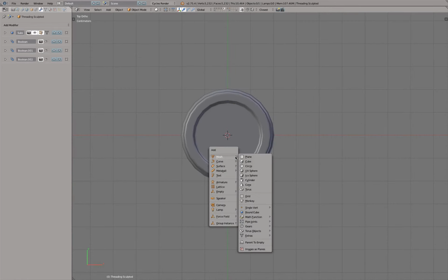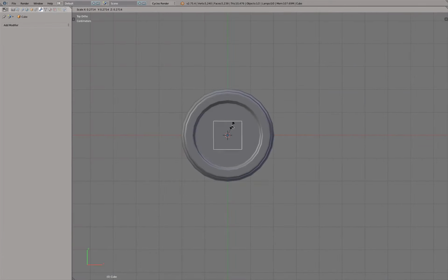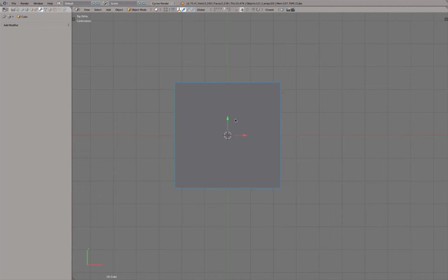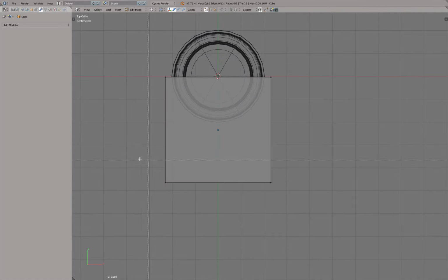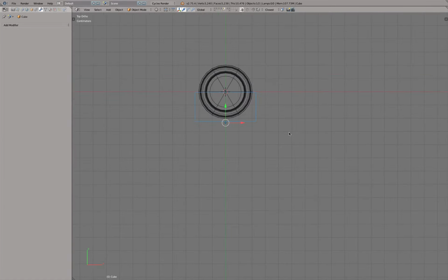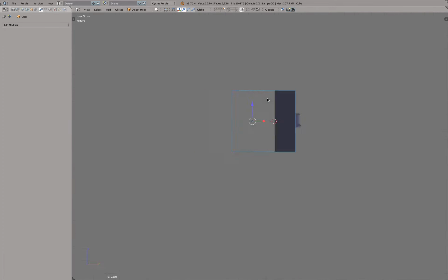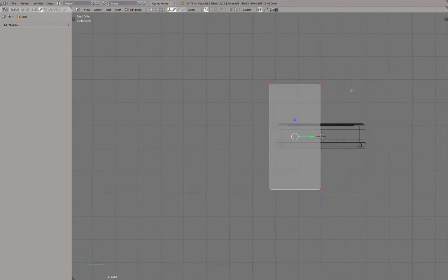So what I can do in this case is the following. I'm going to add a cube, scale it down in object mode, that's fine, till maybe there, and maybe move it to there. I can go into edit mode, move those back up to make it a little bit smaller, and maybe also from the side S and then Z, scale it down.